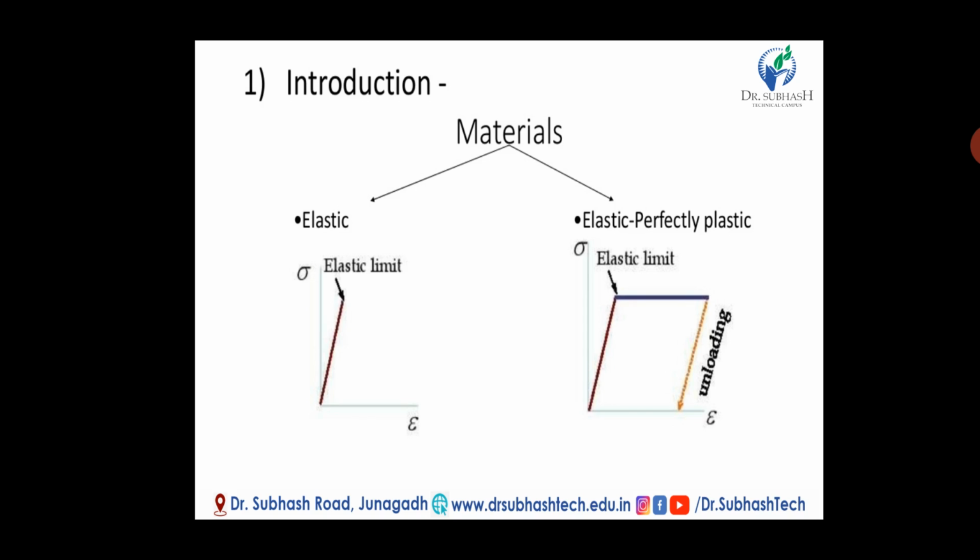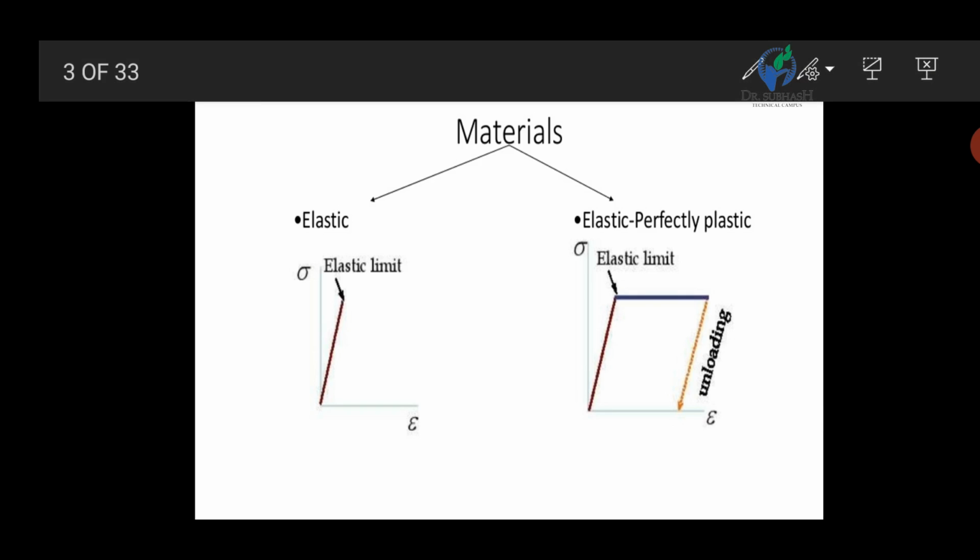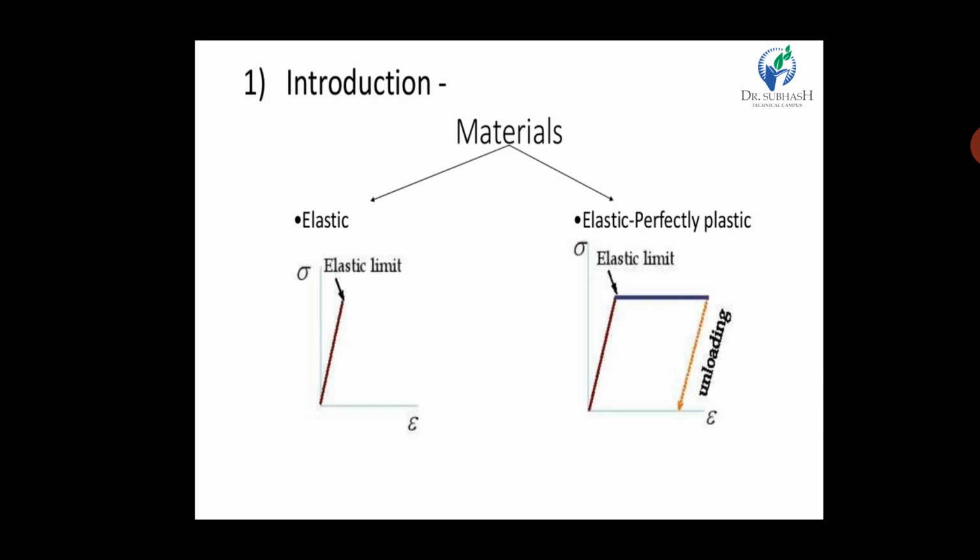The working stress design limits the structural usefulness of steel to allowable or permissible stresses, which are below the elastic limit, called the yield stress, and it is taken as the design criterion. In the plastic method of design, ultimate load is taken as the design criterion, and hence a structure designed using the working stress method may be heavier than one designed by the plastic method.